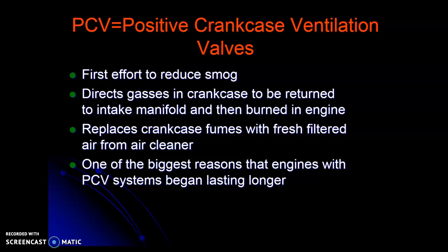Now, fuel moisture is not a good lubricant. It's going to ruin bearings, and the hydrocarbons and fuel evaporate, and on a normal system with a road draft tube, it would just go out to the atmosphere. So they sealed the crankcase and use this PCV system that's going to remove hydrocarbons and moisture from the oil. It also removes pressure from the crankcase. So all that pressure that would push out and cause seals and gaskets to leak no longer happens.